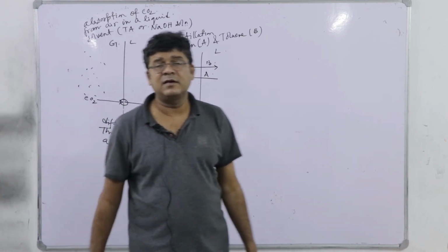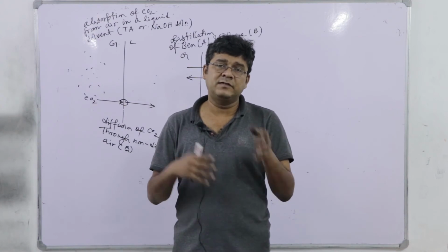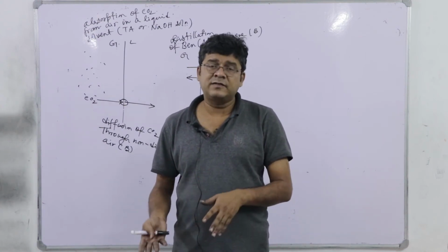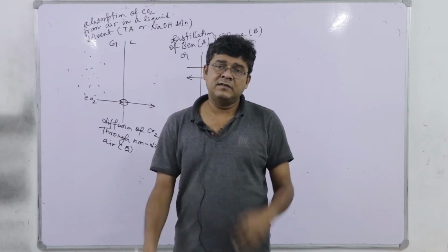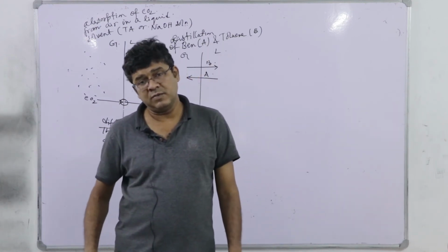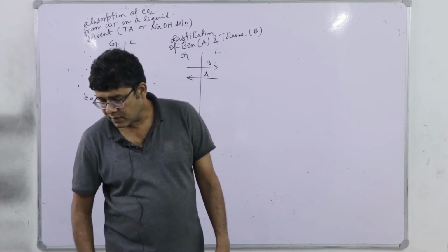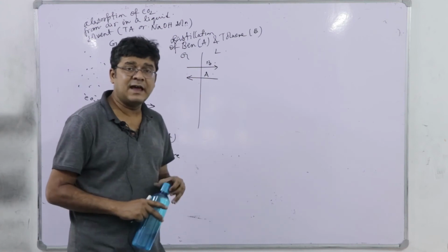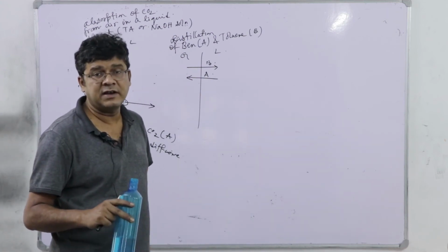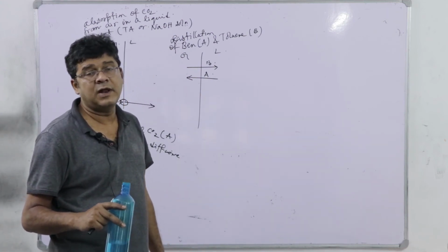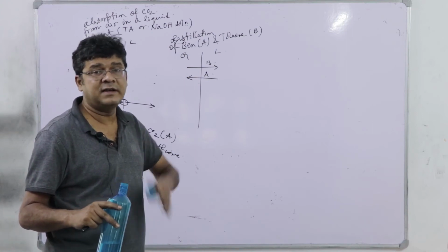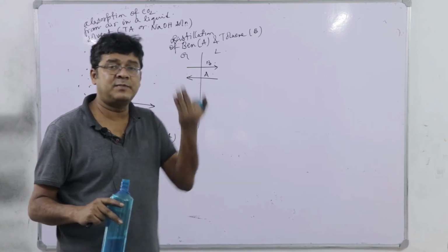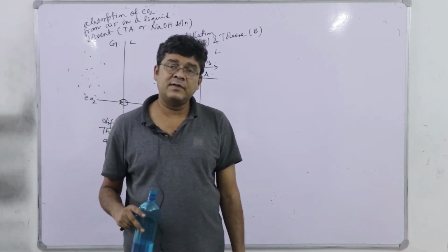So, distillation is a process which we can describe approximately by equimolar counter diffusion, whereas all the other standard mass operations like absorption, humidification, drying, leaching, maybe extraction, everywhere we will have this diffusion of A through non-diffusing B. So, that is why we have chosen the two specific cases to understand those processes very close to the interface, because very close to the interface we will have only the diffusive process. The degree of turbulence or the eddy generation is practically minimized, because close to the interface we have the viscous sublayer.